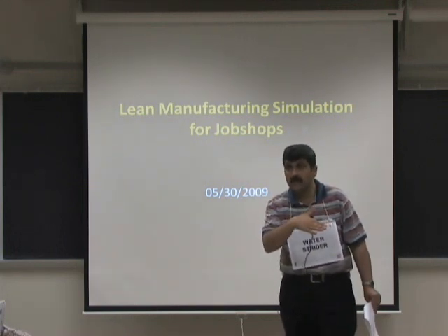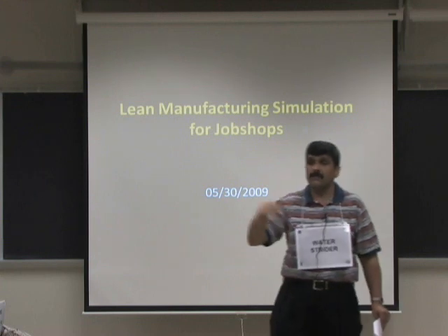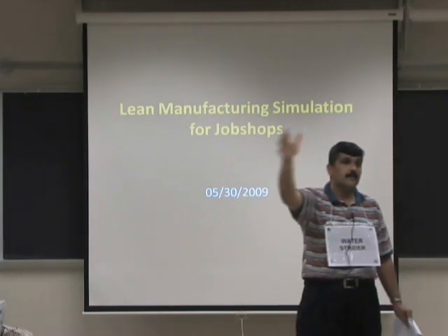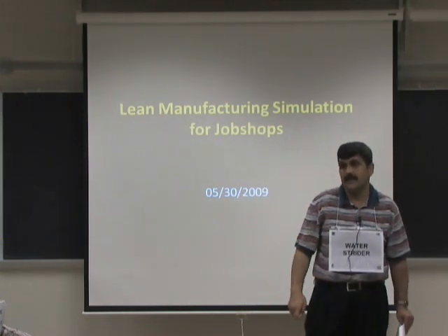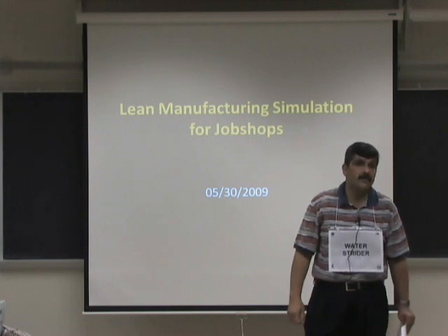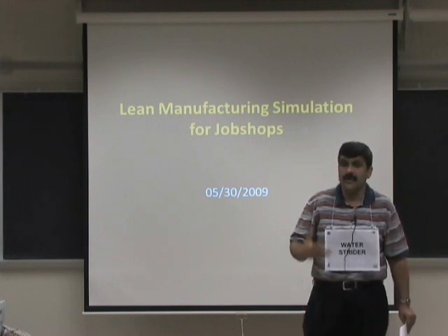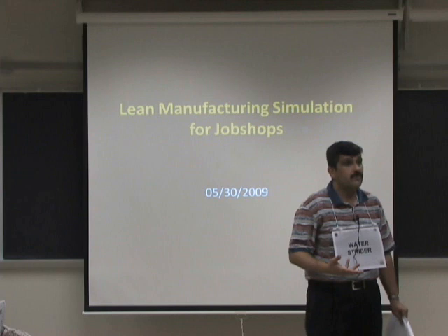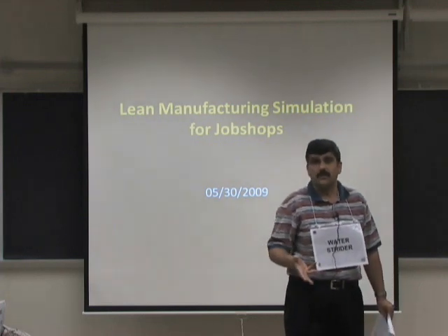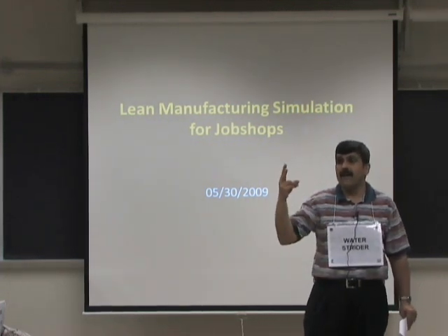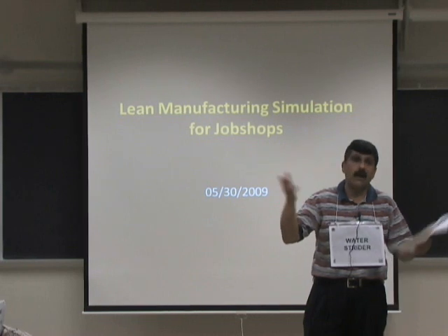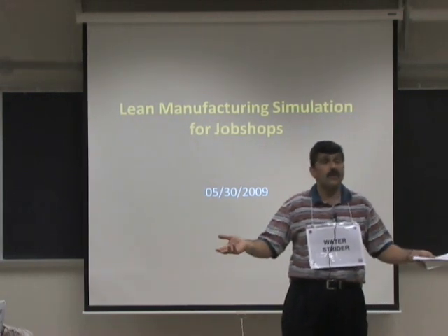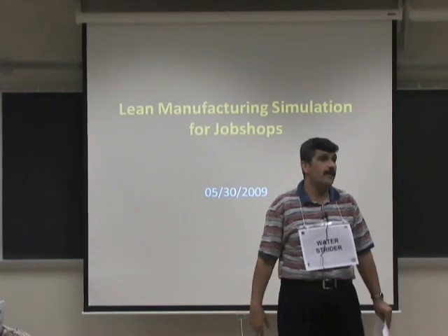They are far more flexible, and they combine the properties of the cell layout on one side and the process layout on the other side. We kind of forget that. That is also important to understand, especially because in a lot of factories, you will have expensive machines. And if you have two product families, each of which requires that machine, you're out of luck. You cannot buy another machine and put one each in those two cells.